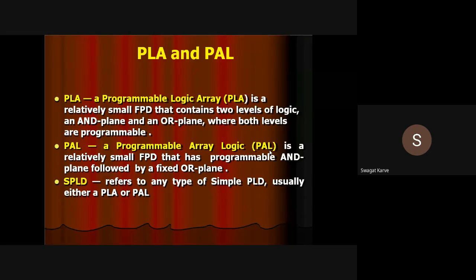Okay, you know this difference. In PLA, both are programmable. And in PAL, the AND is programmable whereas the OR is fixed. And now what about SPLD? It's referred to any simple PLD, usually either PLA or PAL. That means the programmable logic device that can be of PLA or PAL can be known as SPLD.